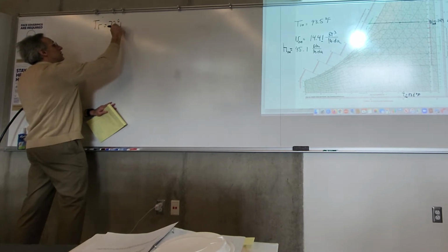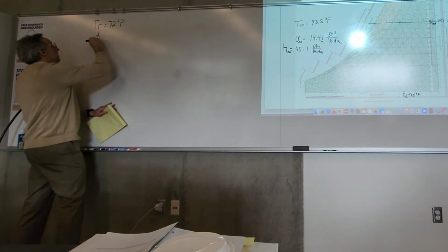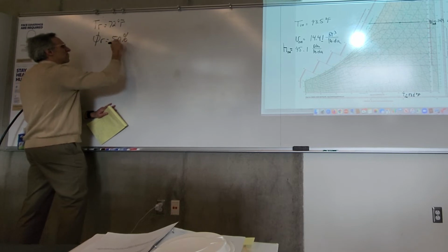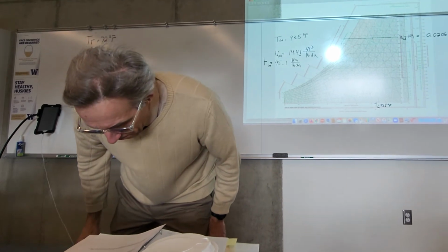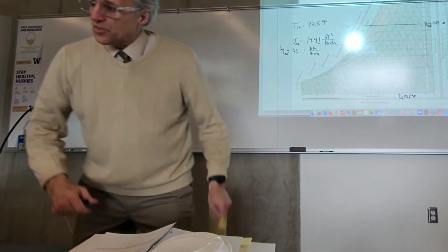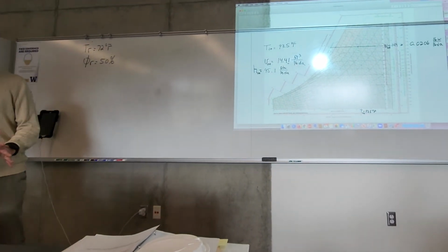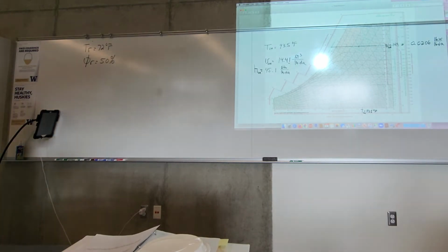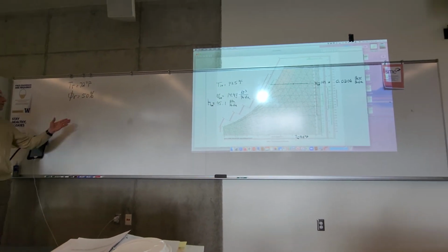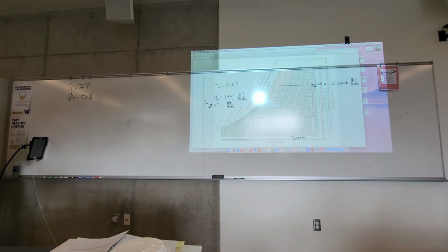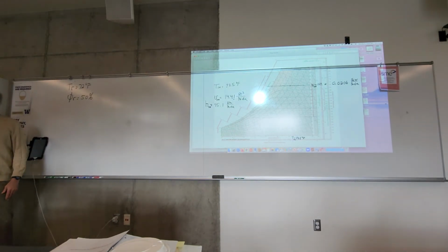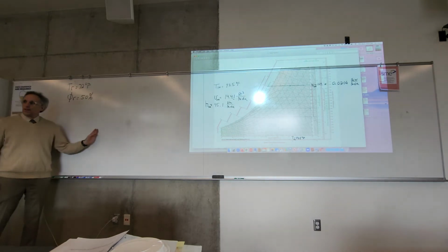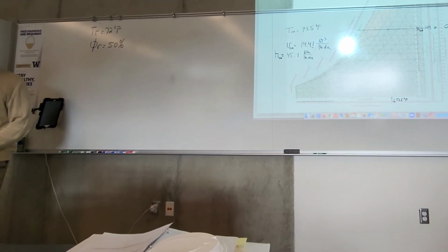In this case, it's going to be 72 degrees and 50% relative humidity. Is that right? Sounds correct. Final say, yeah. So this is a typical design state. Maybe a more energy conscious client will say 75 degrees is fine. But I like cooler. 75 is not comfortable to me, but 72 feels better. 68 even better.